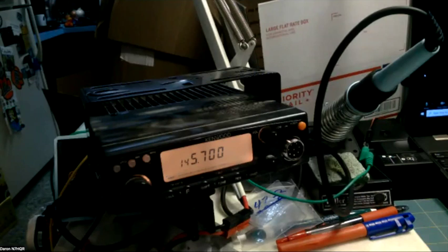That's negative 121 dB right there, where it goes away. So not very much power it takes to open that receiver up a little bit and get a signal in. And that's well under 1 microvolt, correct? Let me see. 0.25 microvolt, yeah, at the radio antenna input.